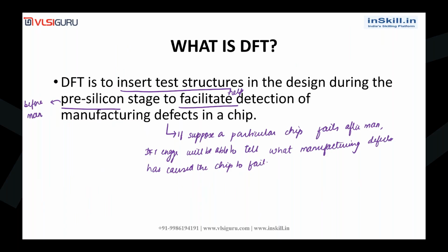So DFT is to insert test structures in the design during the pre-silicon stage to help the detection of manufacturing defects in the chip. So suppose a particular chip fails after manufacturing, DFT engineers will be able to tell what manufacturing defect has caused the chip to fail.